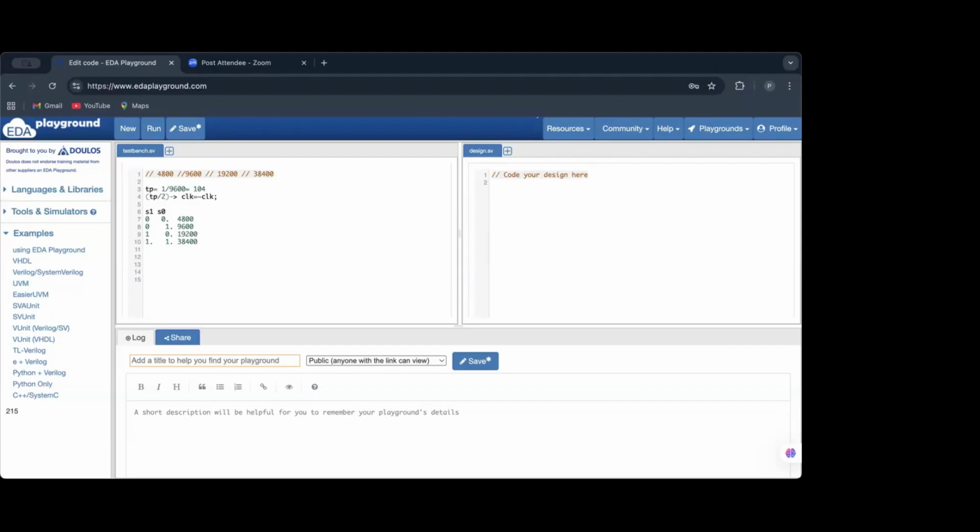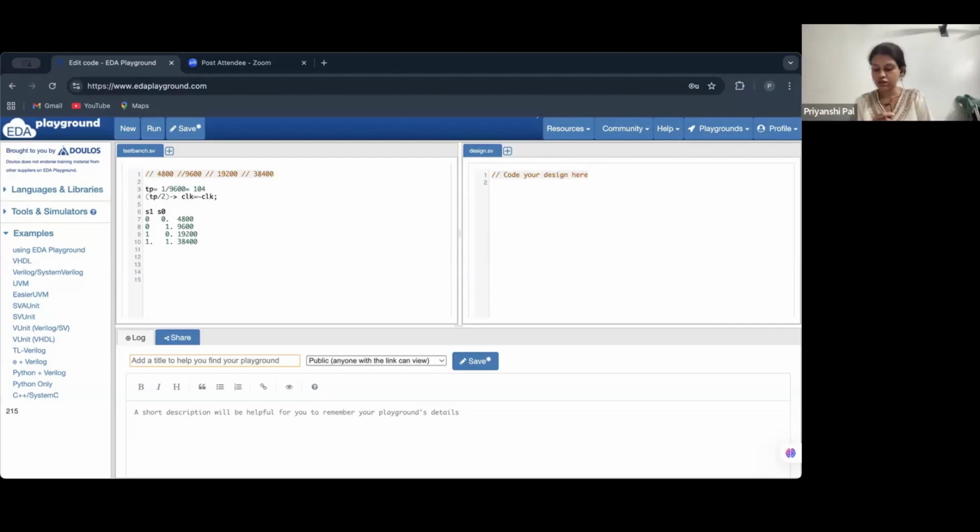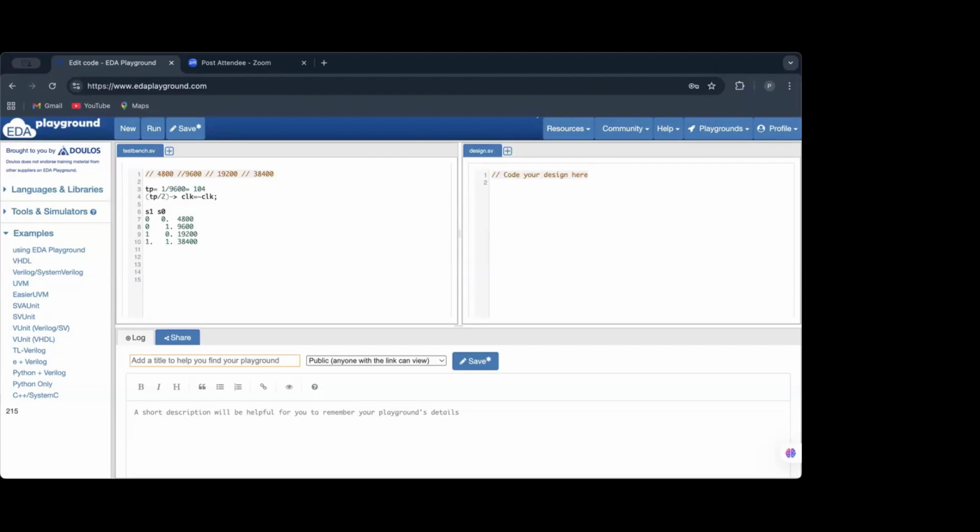Phase. I haven't heard of these. I will look into it. Yes, phase determines whether the data is sampled on the rising edge or the falling edge of the clock signal. And by changing the polarity and phase, we can have different modes of SPI communication.